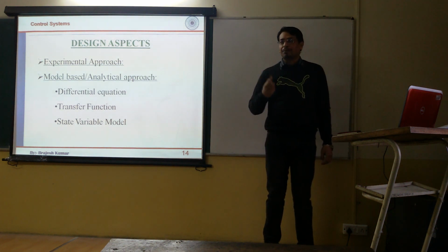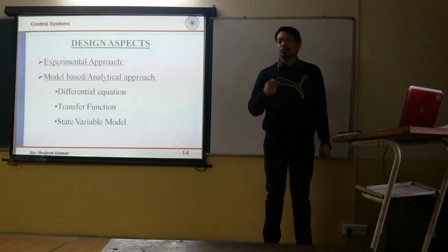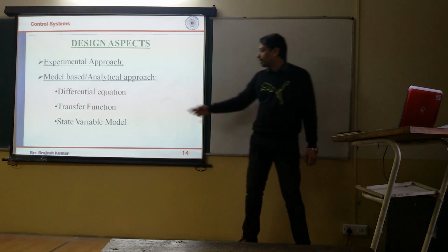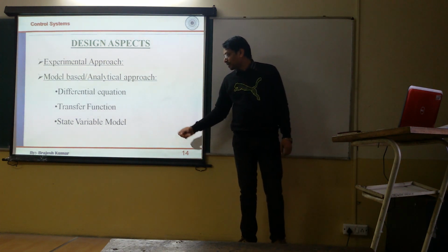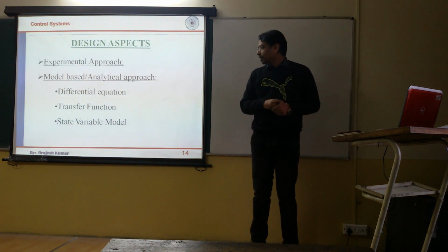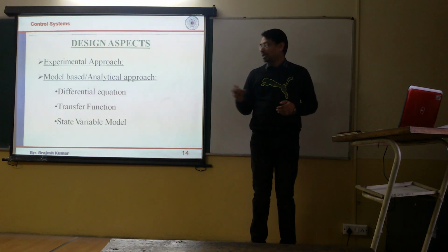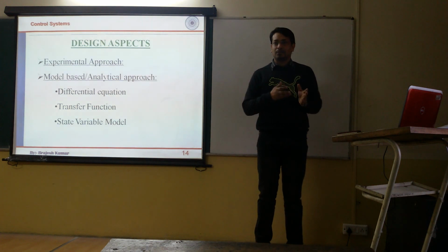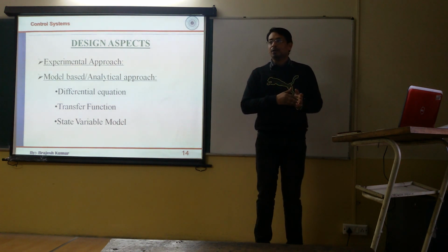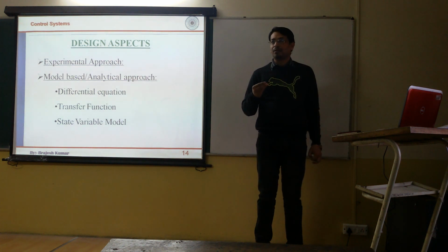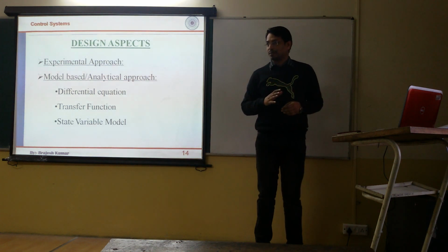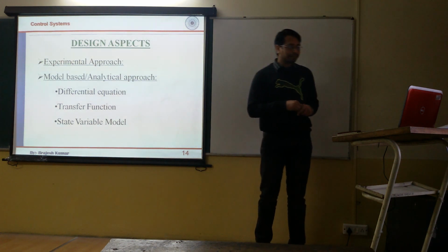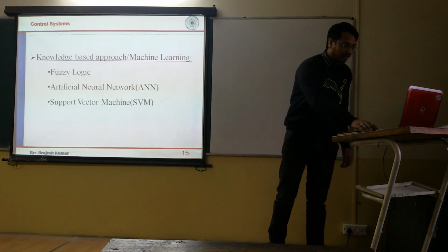A model is something which is going to represent something else. So what you do is capture the dynamics of the system and represent it in a suitable mathematical form. This mathematical form may be a differential equation, or a transfer function, or a state variable method. Later we will see that we can also get the transfer function from the differential equation itself. When you have derived the mathematical model, you can analyze it to know the characteristics of the system. Then you experiment on software, outside the plant, and after the final finished product, you can directly install your controller. So this is your model-based or analytical approach.